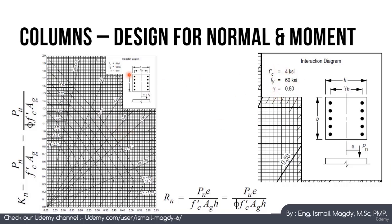Here, these are the main data of this interaction diagram. There is a different interaction diagram for each f'c and fy, and also for each gamma, which is the ratio between the distance between the reinforcement on both sides of the column and the total width of the column. So this is the width minus the cover from each side, and this is the total width of the column.